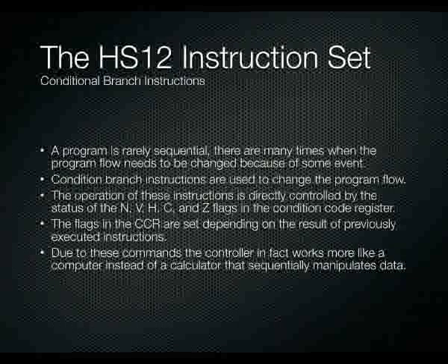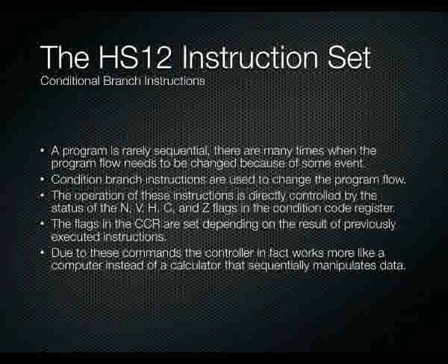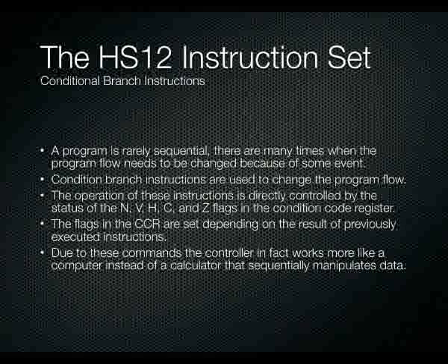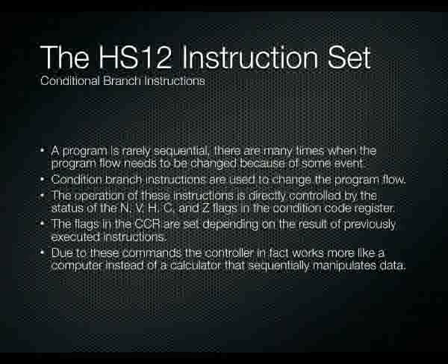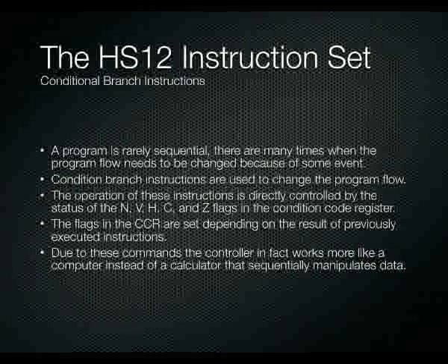Any sort of instruction that we've used beforehand can in fact set the condition code register flag. So therefore, if you really want to branch depending on a comparison, then you have the comparison, then the branch. You don't have a push or a pull or anything else between your compare and your branching, because they can in fact change the status of the condition code register, which means your branch doesn't actually take place. So generally we'll have our compare and then our branch straight after it.